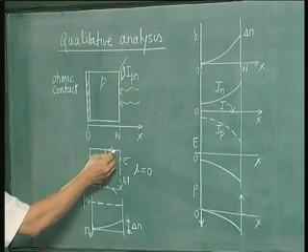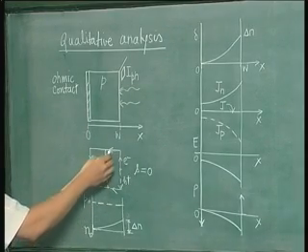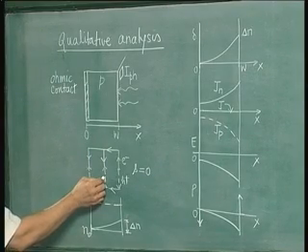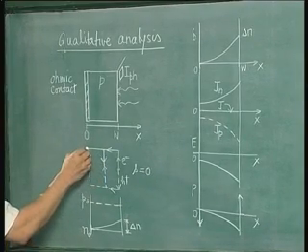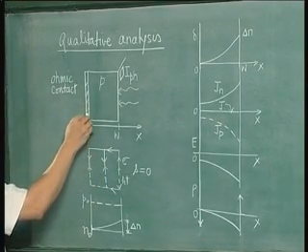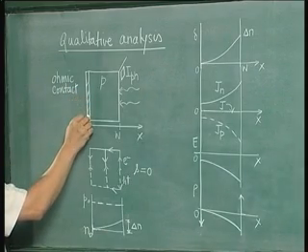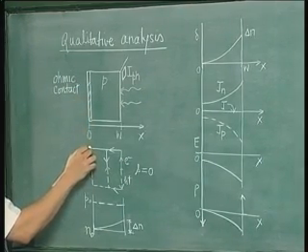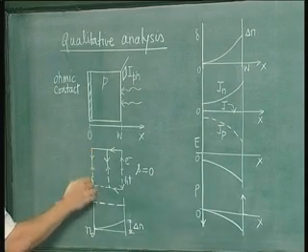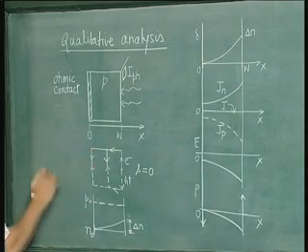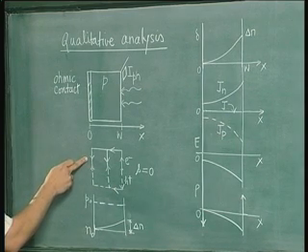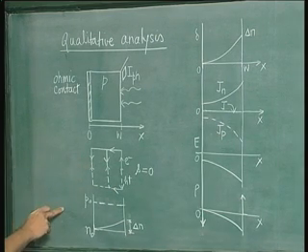Now carriers which are moving inside, what happens is during their motion they also recombine. This is what is shown here. Finally some carriers are still left by the time you come to this particular surface, the contact where the ohmic contact is there. So all the carriers which are remaining until this point will recombine at this contact. Now let us sketch the concentration of holes and electrons based on this picture.